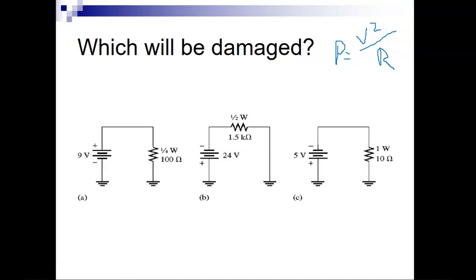It's what? It's 810 milliwatts. So will my resistor here be damaged at only a quarter watt power? Yes, it is. Do the math. Yep, this guy right here is busted.